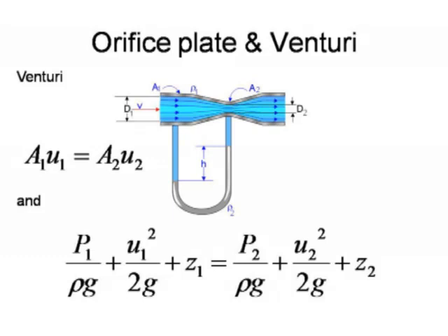Well, we have our two famous equations here in fluid mechanics. The continuity equation at the top there, which says that what flow goes in comes out: A1 U1 equals A2 U2, so A's area and U's velocity. So the two of them together are meters cubed per second flow through position 1 and meters cubed per second flow through position 2.